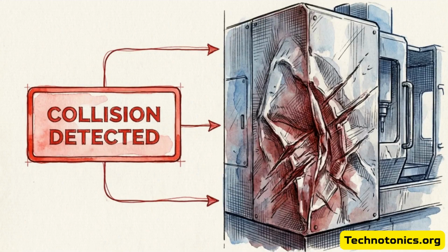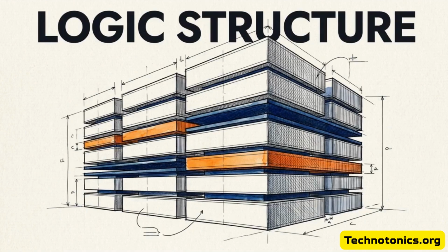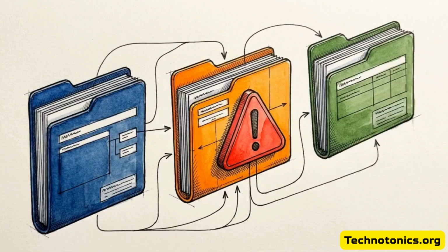floor. As your projects scale in complexity, the program tree can quickly degenerate into an unreadable list of tangled commands. Step 5 solves this by breaking down those massive sequences into small, logical modules. We create distinct separation for individual actions, like pick, move, and place. Structuring the logic into a modular architecture means when an error occurs, you know exactly which segment to check.